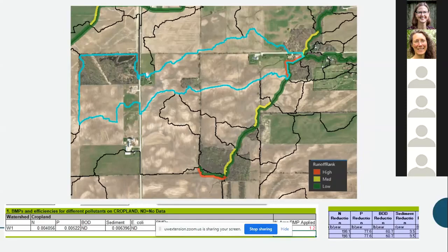So you can select applicable riparian catchments for the proposed buffers and export just the desired ones. You will want to review the riparian catchments chosen for accuracy and to look for ones that may include large drainages that are actually going to channelize flow, such as this catchment highlighted in blue here. You can see that a lot of this drainage is actually just going to this channel here and is probably not really going to be treated if you were to put a buffer here.